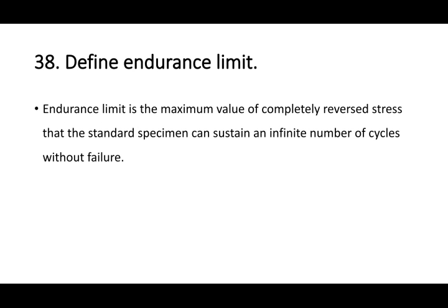Next question. Define endurance limit. Endurance limit is the maximum value of completely reversed stress that the standard specimen can sustain for an infinite number of cycles without failure. That is known as endurance limit.